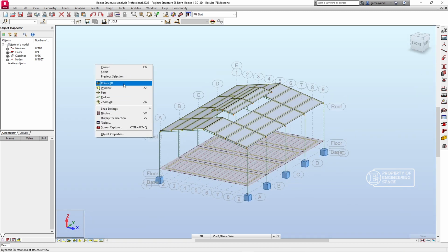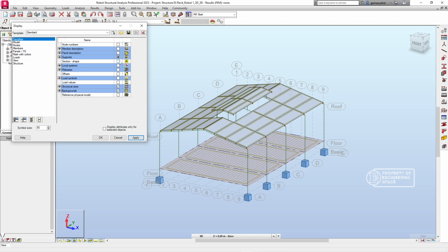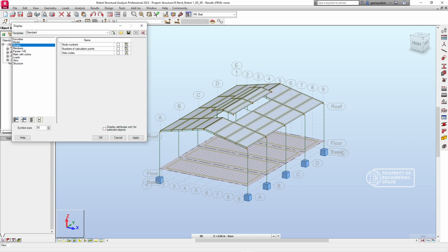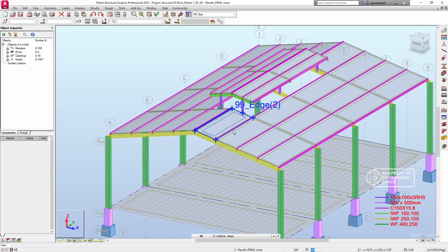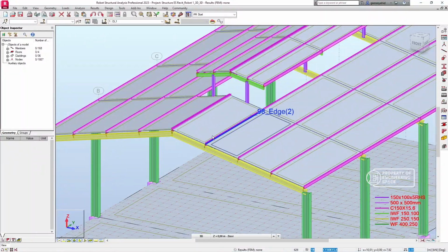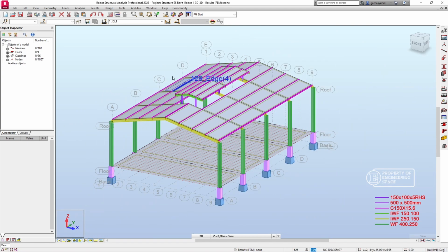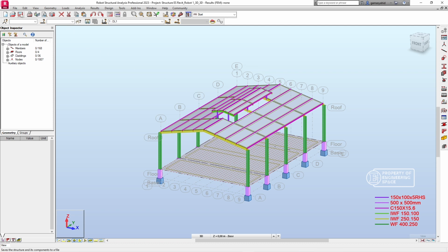So we go to properties again, go to display, section set, turn on, goes with offset, and then the member shape, and also legend by colors. Alright, now our design was completely good and fulfills the whole of actual design. Now let me save it first.